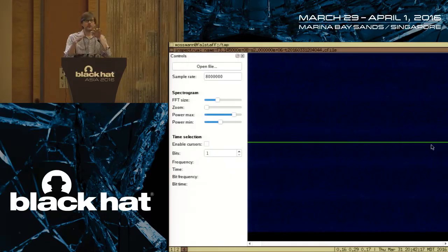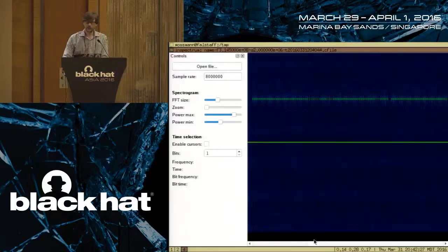So basically, we took that plot, we turned it sideways, and now we have a whole bunch of information in 2 dimensions instead of just looking in 1 dimension. If I scroll over to the right, you see here I have an event that I can scroll around and see what's going on. Higher frequencies are further up. This center frequency, this green line, is 314.5 megahertz. That's what I was tuned to. And up here is 314.98 megahertz where we detected this.